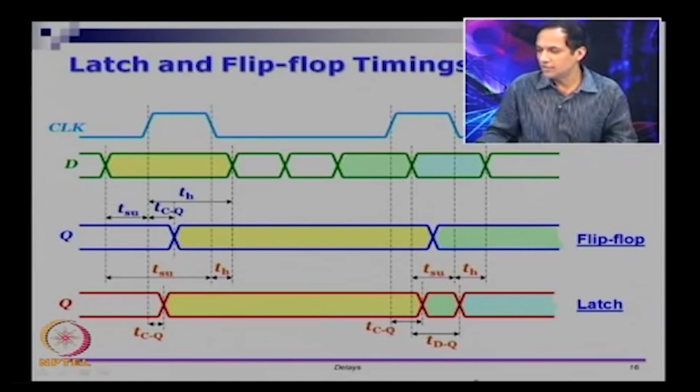and now the clock is remaining stable at 1, the latch is enabled, you are changing Q. At this point it does not make sense to go and measure clock to Q. Now, you should measure D to Q because data is changing, the latch enable is kept constant. So, you measure D to Q. So, this is another factor that is necessary for a latch.